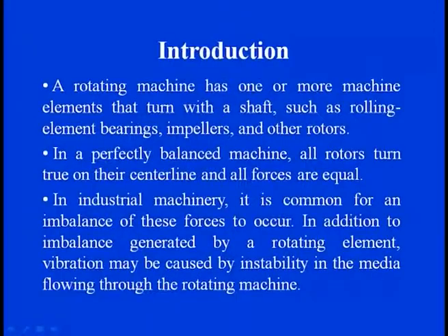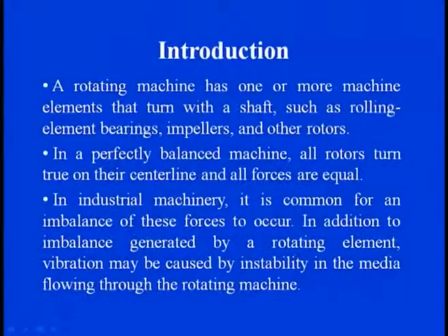All these contribute some part, or even a significant part, of the vibrations. When we talk about a balanced machine, all these features are in the coplane and collinear with the center line, the axis of rotation, and the forces which are generated can be well balanced.